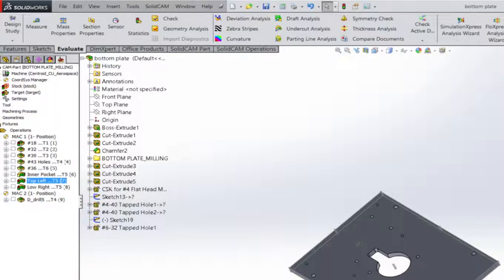All right. Homework 14, which is assigned today and due tomorrow: I want you to create drilling tool paths, like this one that I just did, for your part. If you want to, you can even go drill your holes. You are now clamped on there. You have seen enough. You've been able to set part zeros, set tool zeros, and did you even run a path or no? Didn't run a path, but you're close. If you want to, with our help, you can go ahead and even run some holes on the machine.